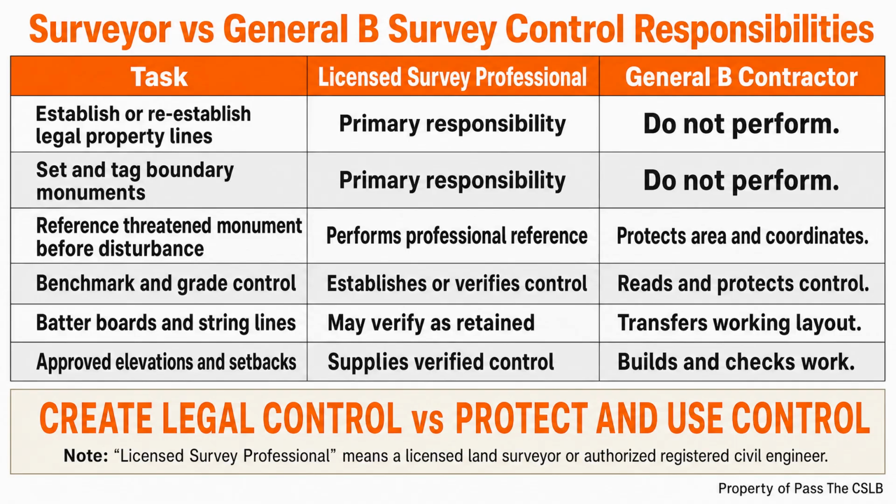A benchmark matters only if the crew can return to it and get the same answer. That means the reference has to remain stable, identifiable, and protected from grading, demolition, traffic, and material storage. A benchmark that gets buried under spoils or knocked loose by equipment is no longer reliable control.